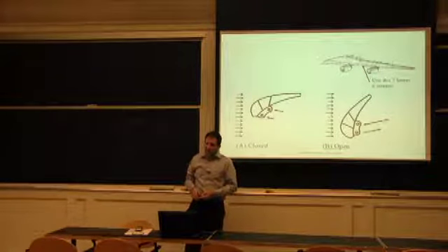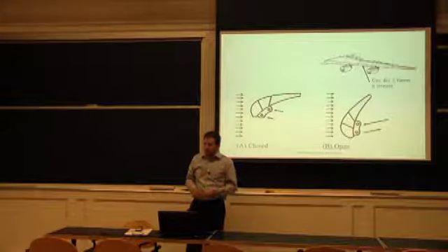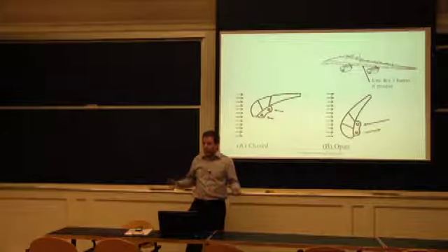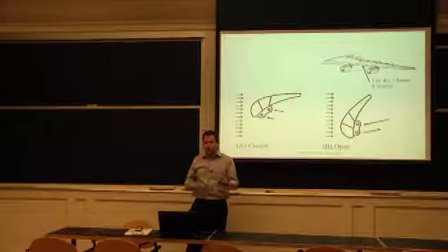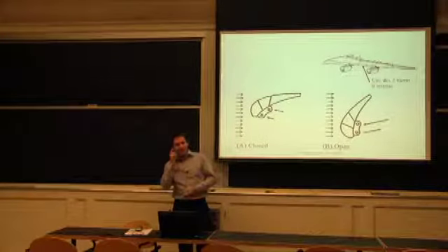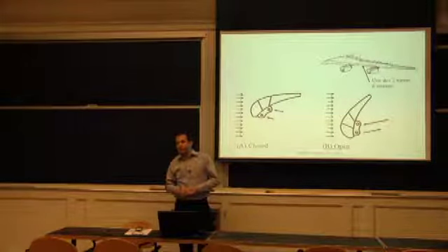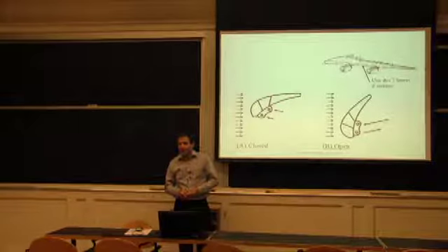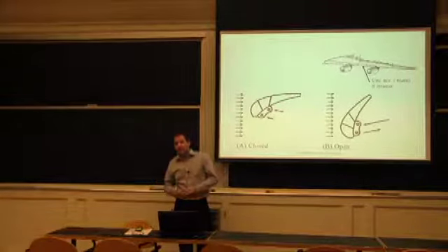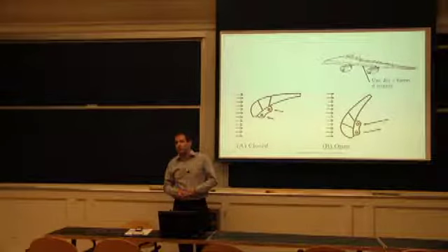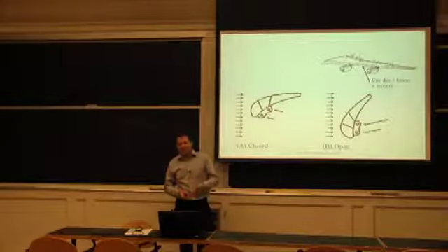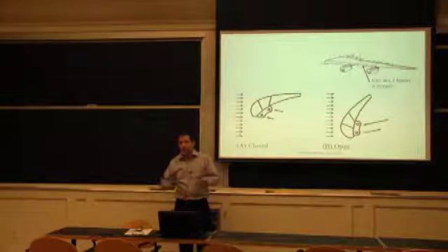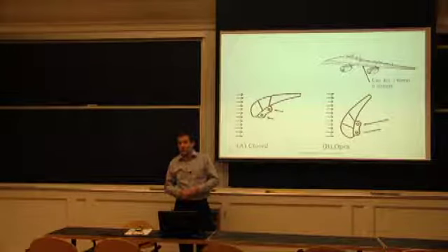And they may have increased the displacement after you get more compliance out of it. But it's very severe testing, if you ask me, for an assembly to go through. But it was critical. If you start popping rivets in one specific location, now you go back and say, my analysis didn't predict that, so what did I do wrong? Because it's definitely happening now. So it's a good way for complex assemblies to really say, hey, we're giving this a shot. This is supposed to be a relatively optimized design. We take these other low points, and then you test it out and find out, is that really the case?